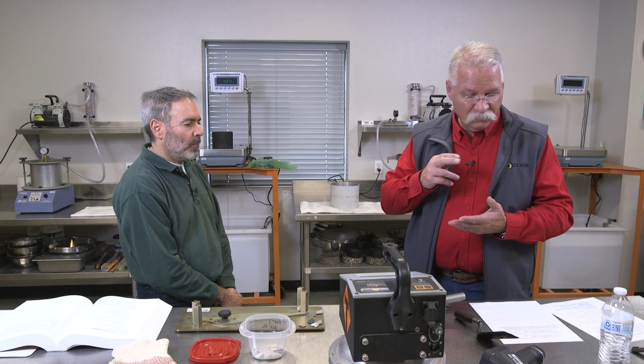And the key there is, if your asphalt content is too high or your gradation is a little off, I can look at my test results and say, all right, what's going on? But if I've got 4 or 5 different sticky notes, I've got to piece them together. Am I running my C-rock bin too hot? That's just not professional.